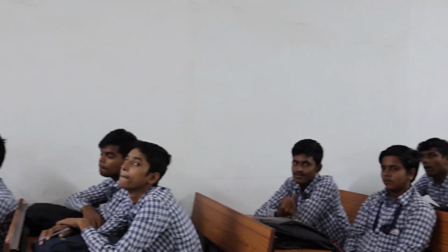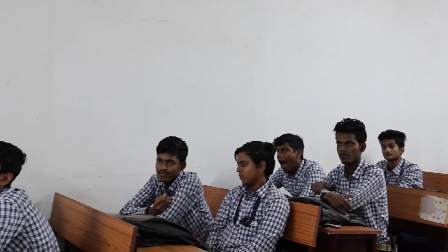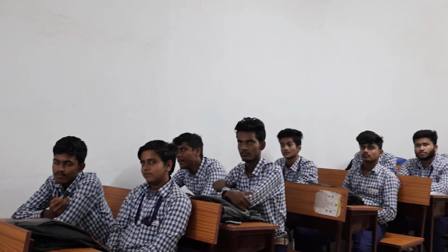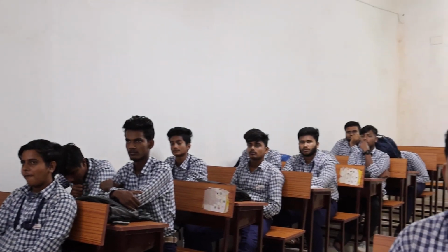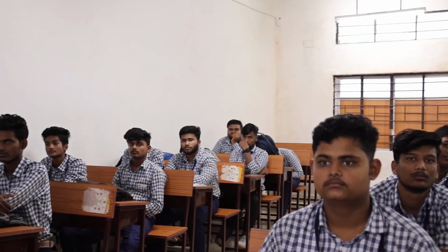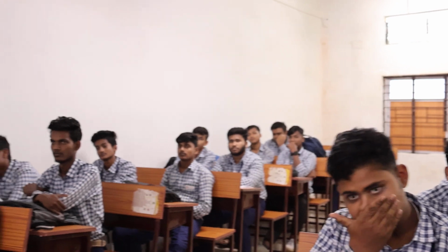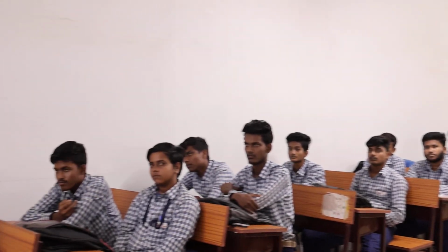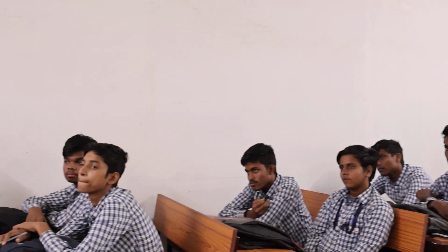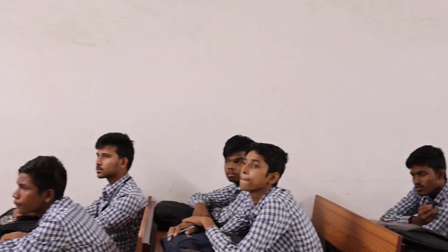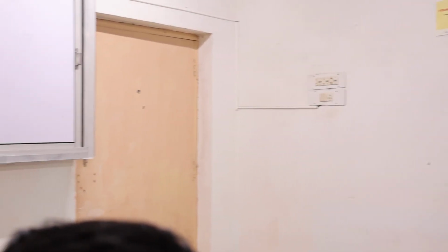So this is the efficiency of the Otto cycle. If someone asks you what is the efficiency of the Otto cycle, then efficiency of the Otto cycle equals 1 minus 1 by rc to the power gamma minus 1. These are the three efficiencies. The first one is 1 minus 1 by rc to the power gamma minus 1. The second one is 1 minus (T4 minus T1) divided by (T3 minus T2).